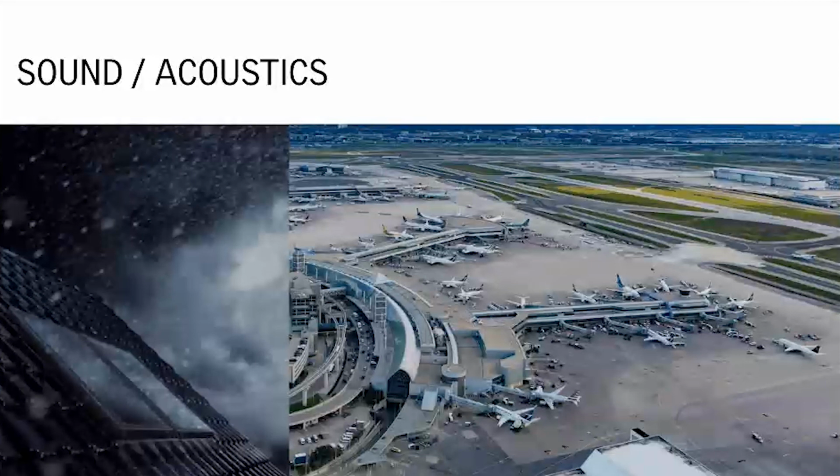Well, one of the ways to deal with it is very similar to how you would deal with thermal efficiency. So adding panes of glass, adding laminate to the glass are very good strategies to start with. Varying the pane thickness, so each individual pane being a different thickness also helps. And if you're a triple pane, you can vary the airspace depth, and all this will help reduce the sound transmission through the glass. Now, the last one is also good for energy efficiency, is make the skylight more airtight. Make sure the install is more airtight, and you'll have less sound transmission through that glass.